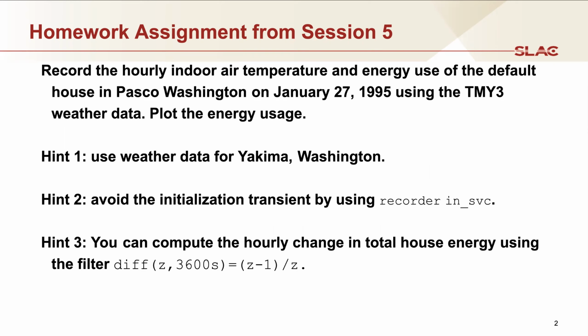There are various transfer functions, and over time you kind of learn which ones do this, but you can look this up at Wikipedia as well. These are sort of standard definitions for various commonly used transfer functions, integrators, delays, and then this one, difference, which is z minus 1 over z. And that definition with the time step of 3600 seconds gives you a 1 hour time difference.